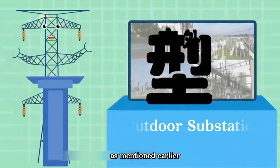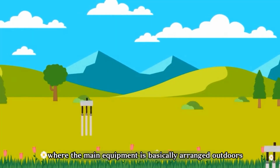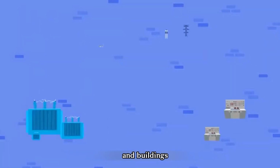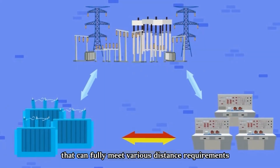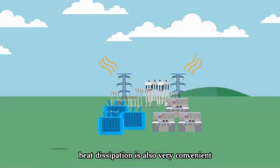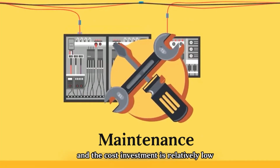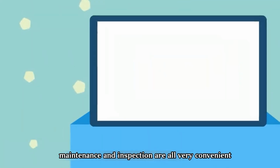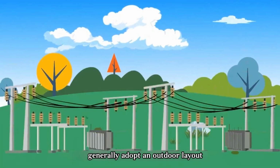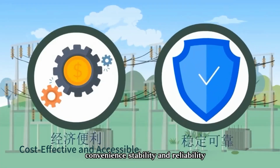As mentioned earlier, an outdoor substation refers to one where the main equipment is basically arranged outdoors. Its characteristics include a large footprint, electrical installations and buildings that can fully meet various distance requirements, such as electrical safety clearances and fire separation distances. Heat dissipation is also very convenient, and the cost investment is relatively low. Operation, maintenance, and inspection are all very convenient. Substations with higher voltage levels generally adopt an outdoor layout, considering its advantages of economy, convenience, stability, and reliability.